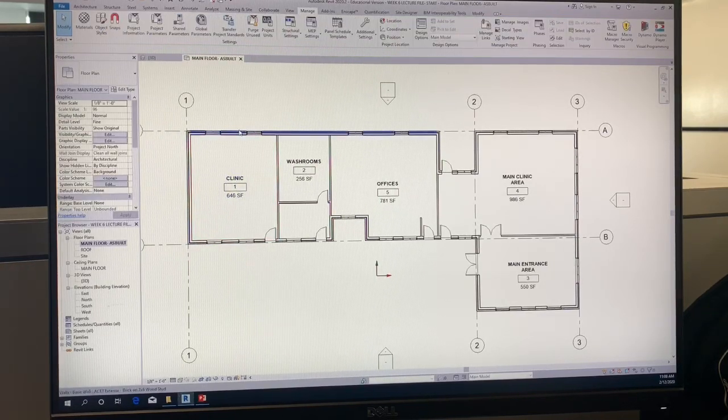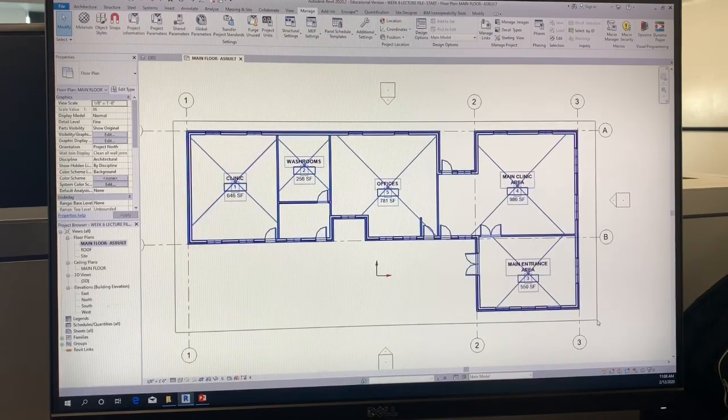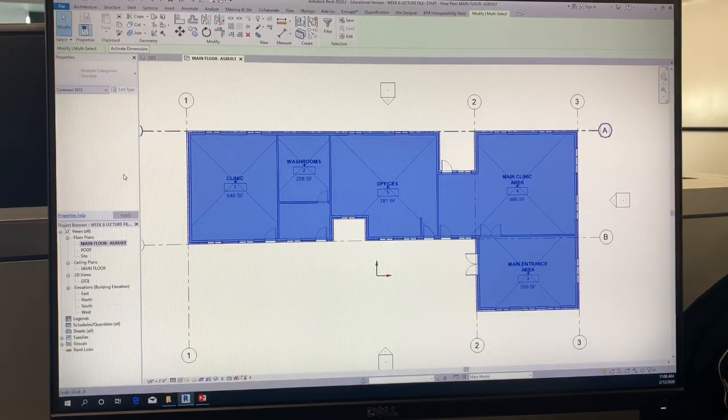So when I try to select all my items, go ahead and try to select all your items like that. You'll notice that it's not going to give me the option to change the phasing, because I'm selecting items that do not have a phasing. Like, again, the room labels, or perhaps a room separator line or something like that, that is not part of the model.